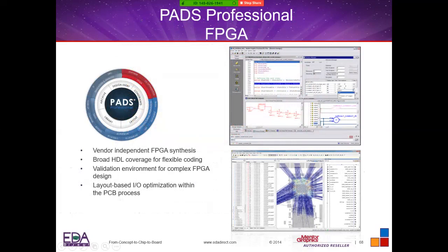Instead of you doing all that pin swapping when you get into these huge BGAs, we can actually go in, work with the FPGA engineer, and move blocks of pins so that we can escape easily out of the BGA, making routing a lot more smooth, a lot more professional, rather than doing all that manual pin swapping just to get to your traces outside of these huge BGAs that are now being designed. Highly recommend that if you've got like 2,000 pin BGAs that you're using.